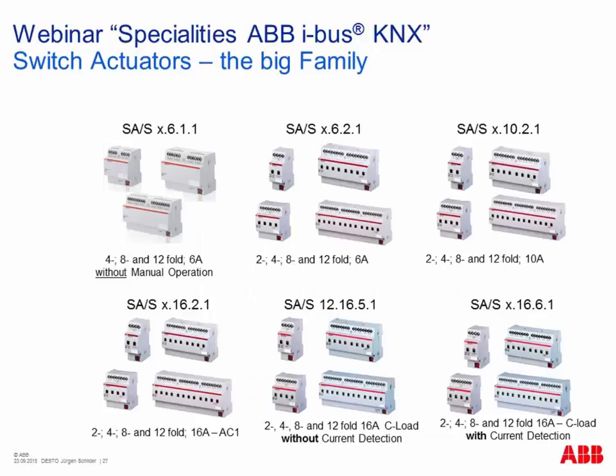Switch actuators, I think well known, but a small summary here. We have a big range, a big family of KNX switch actuators, starting from 6 ampere up to 20 ampere, also with high inrush current. So startup current is a topic depending on the load. From 2 up to 12 channels in one device.